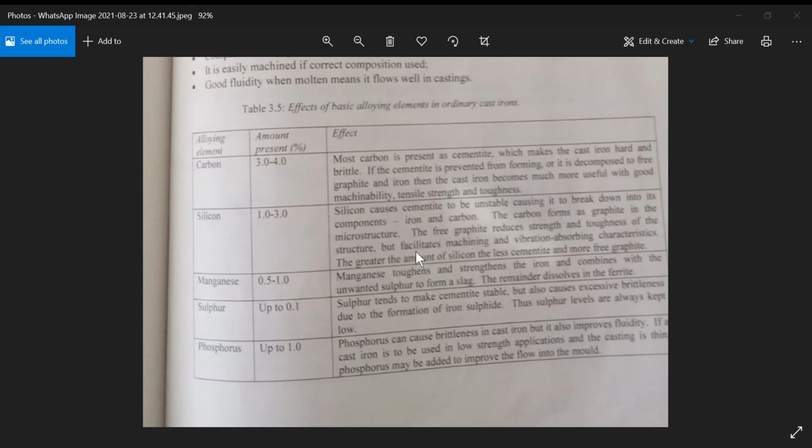Okay, and we go through that here a bit more. The graphite flakes are essentially voids in the structure filled with graphite, which has little mechanical strength, and they have sharp edges and ends.